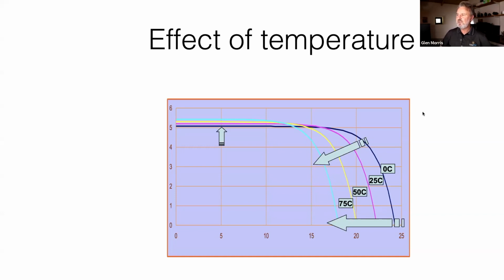Richard says, most thin film module data sheets show a low temperature coefficient, but only if the temperature range is 25 to 75. Do you know why the minimum is 25? Well, that'll be a manufacturer's issue. They may actually not warrant the panel for very cold conditions. I'm not really sure what the answer to that one is. I would like to look more closely at the data sheets. Thin film is a broad range of products, including things like flexible panels, things which really aren't designed for permanent installations. So maybe they're not robust enough for really cold conditions.